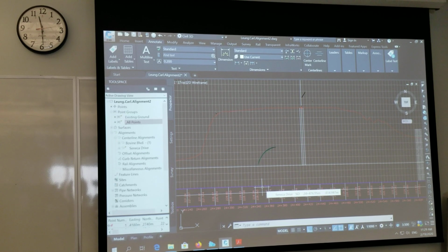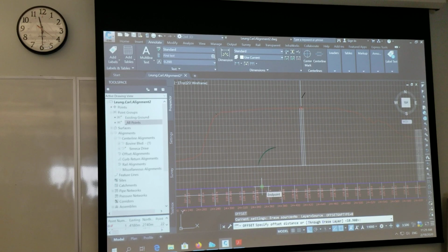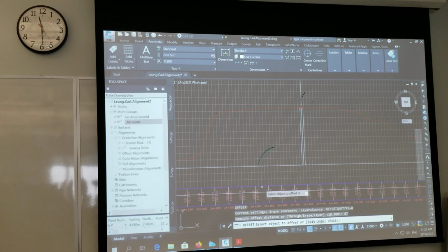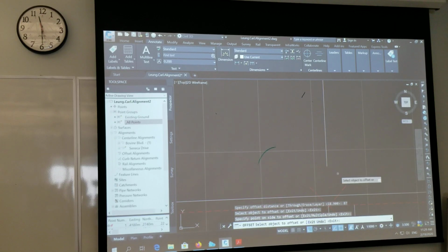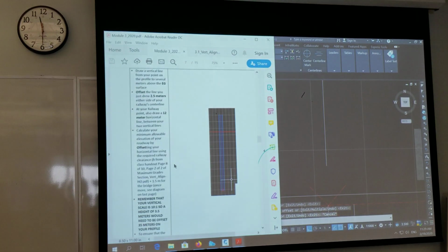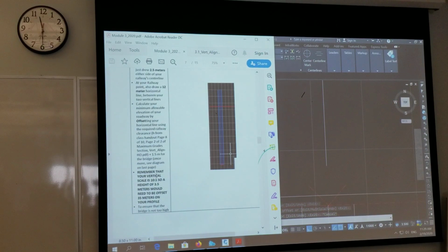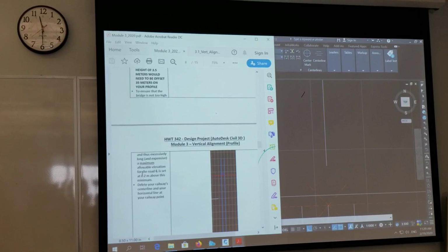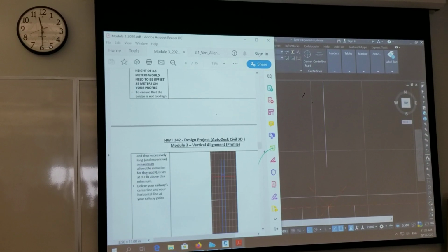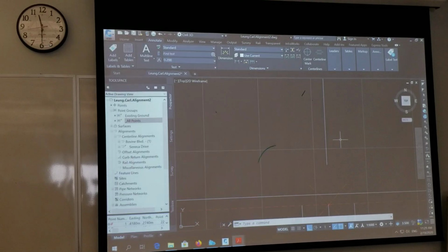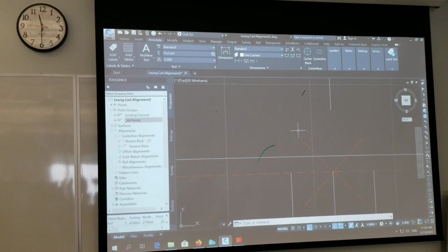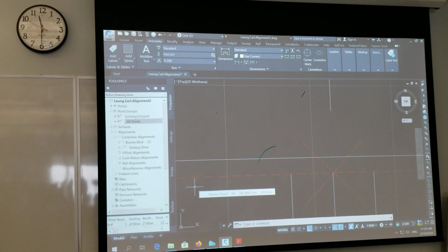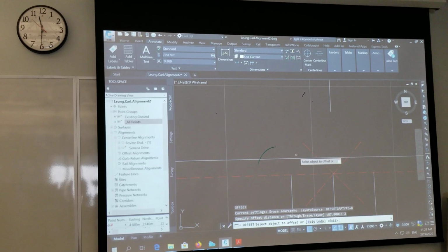7.2 plus 1.5? 8.7. I want to offset 8.7, but because I have this vertical exaggeration, how much do I need to offset by? 87. I'm going to offset this by there, so this is going to be the bottom of it. And I think I need also another, remember the vertical clearance is too high, 0.2. And the minimum allowable elevation for the bridge itself would be 0.2. So I need to offset 0.2 over here, but 0.2 is going to be what? 2. I will explain to you again what's happening.